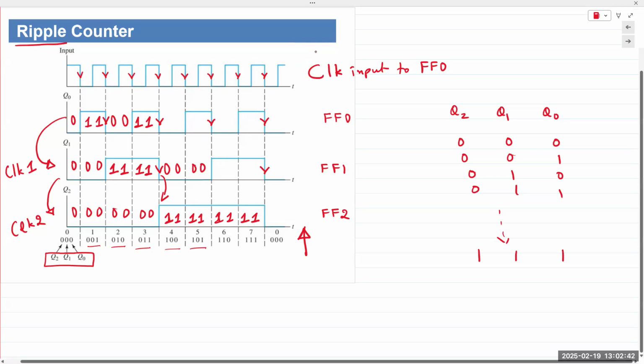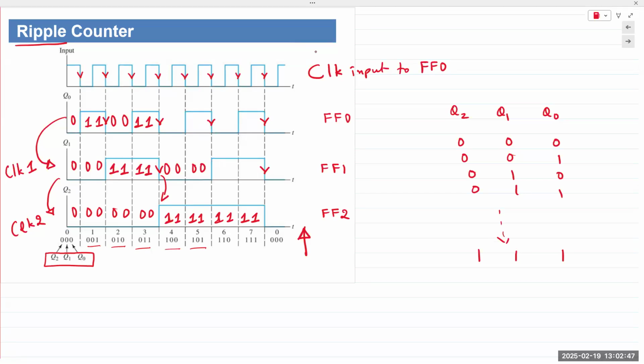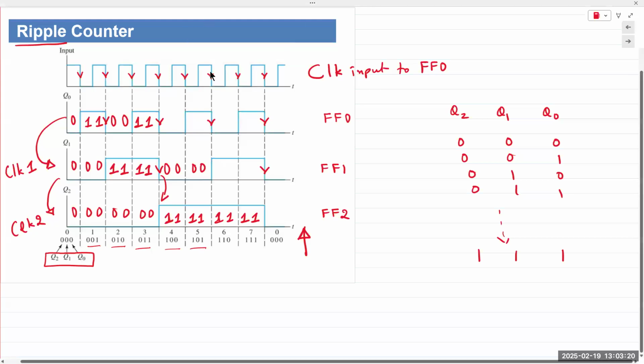Sure, okay. So binary or logic circuits will always start at 0. So it will always end with an odd number. A 2-bit counter would end at 3. 3 would be the 4th state. So 0, 1, 2, 3. A 1-bit counter would simply end at 1. So 0 and then 1. Okay. A 2-bit counter would end at 3, which is the 4th state. 0, 1, 2, 3. A 3-bit counter would end at 7, which is 0, 1, 2, 3, 4, 5, 6, 7. We always have one more state then. No. So at state 6, there would be 1, 1, 0. Yes.